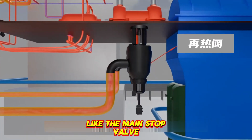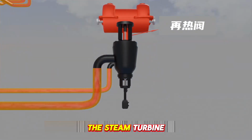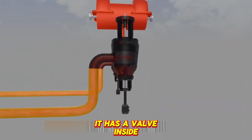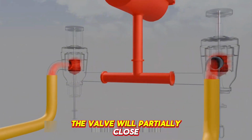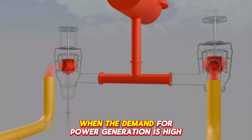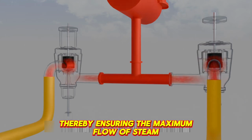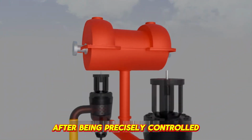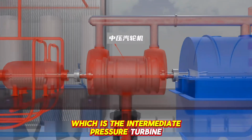Like the main stop valve, the reheat valve can also control the flow of steam entering the steam turbine. It has a valve inside. When the demand for power generation is low, the valve will partially close in order to limit the steam's flow and pressure. When the demand for power generation is high, the valve will open completely, thereby ensuring the maximum flow of steam. After being precisely controlled, the steam then enters the next turbine, which is the intermediate pressure turbine.